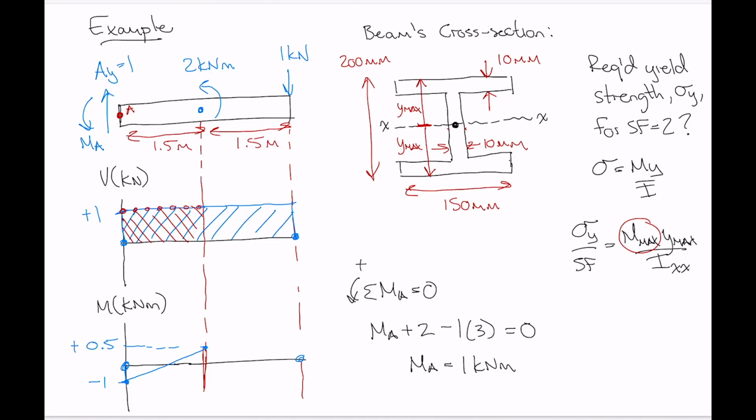Okay, now we get to the 2 kilonewton meter point moment on our beam, and that's again in the counterclockwise direction, so that's a jump down. We are jumping down by 2, so that takes us down to, what, -1.5. And then we're in the next section of the beam, where the value of shear remains a constant positive value. So the slope of the moment diagram has to be a constant positive slope, and that should take us back to 0.